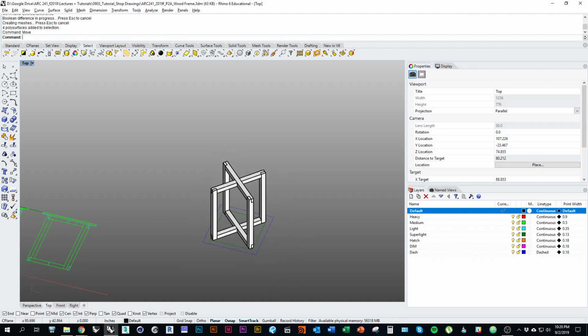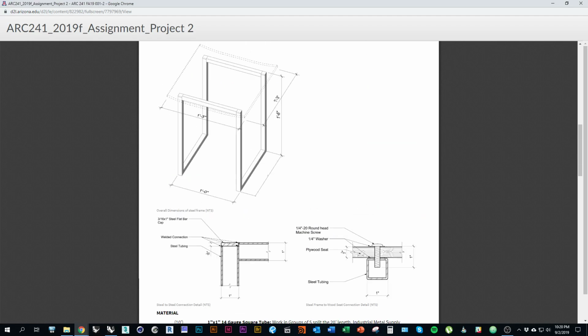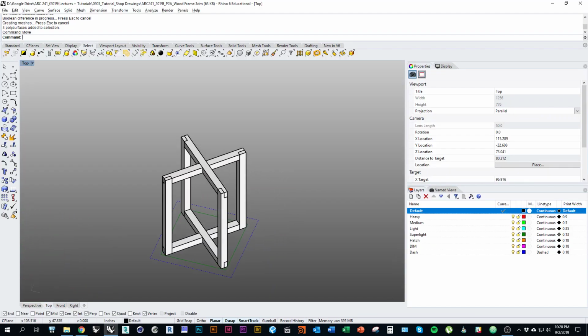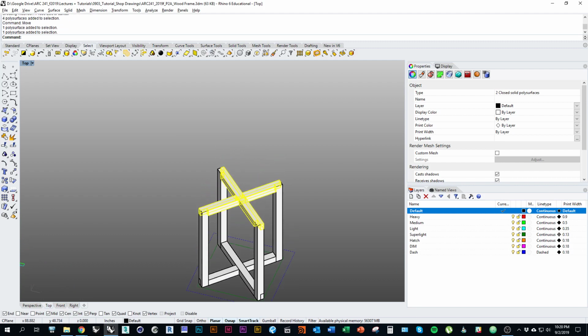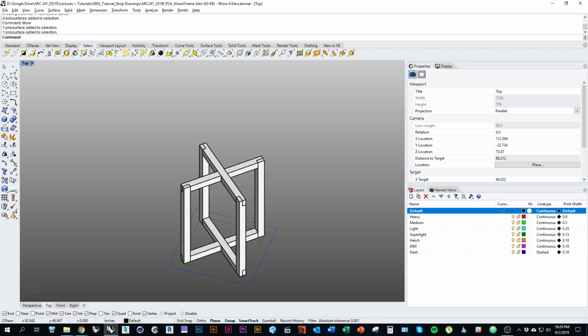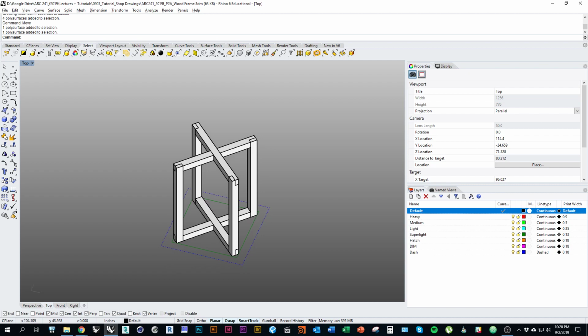and how they all fit together. So what I want to do is take a couple of the members of the 3D model and explode them before I make the drawing. Excuse me. So I'm going to take these, well, first I want to actually choose my angle. So when you're going from a 3D model to a 2D drawing, you always want to choose a drawing angle and you want to save it.